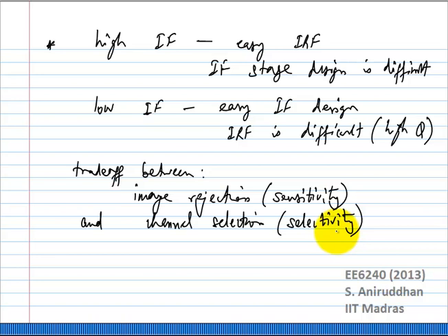Yes, but any loss that the filter has will directly add to your noise figure. Of course you can, right? But normally you do not want to put anything, as much as possible the LNA should be the first component, right? You have already put in a band select filter because you don't want to have out of band interferers. If you need to put in one more filter, that makes it all the more tougher.